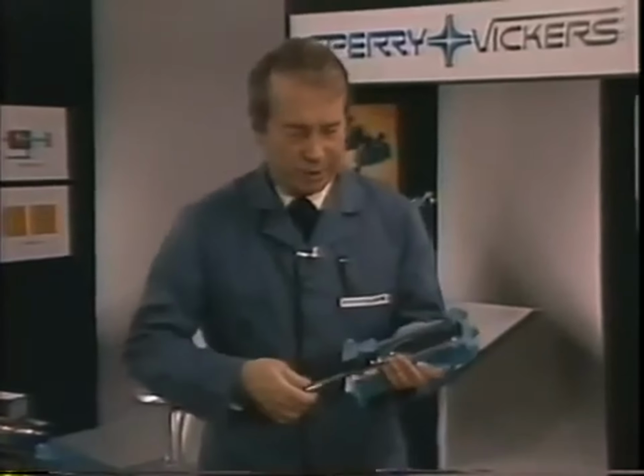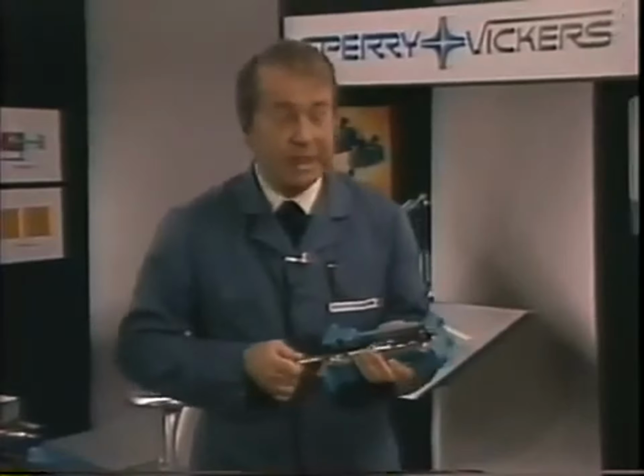Basically, there are 2 motions we can achieve hydraulically. We can move something in a straight line, or we can make something rotate. A cylinder, or linear actuator, provides the straight line motion. It can be single-acting, like a hydraulic jack, where the weight of the car brings it back down, or double-acting, where the piston is forced both forward and backward in its bore by fluid under pressure.